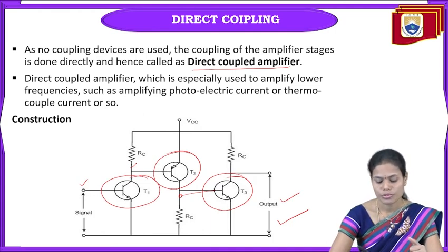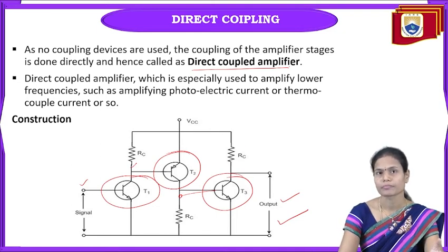Suppose the collector current IC flowing in the T1 transistor is positive, then the collector current flowing in the PNP transistor is negative here. So any variations or fluctuations in these two stages are nullified by these positive and negative polarities. Those will be compensated so that we will get the final overall gain across the output.